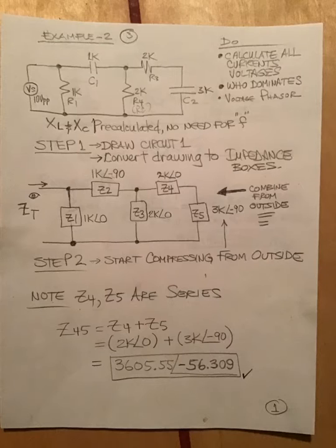So what we're going to do here is calculate all the currents and all the voltages. We're going to determine who dominates. ZT will tell us that. And we'll do a voltage phasor at the end just for fun, just to wrap it all up.